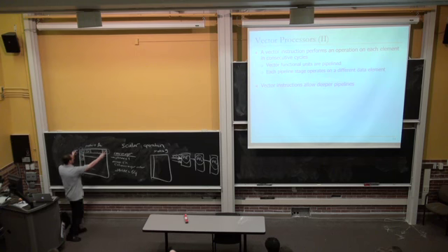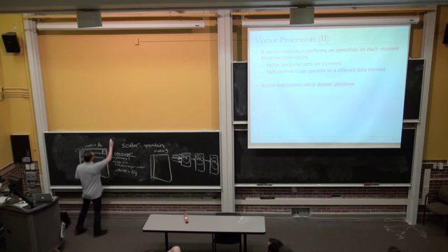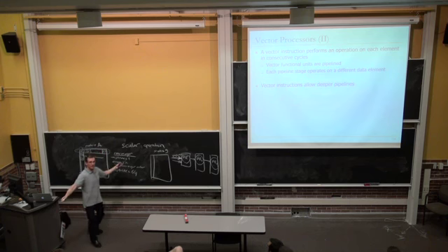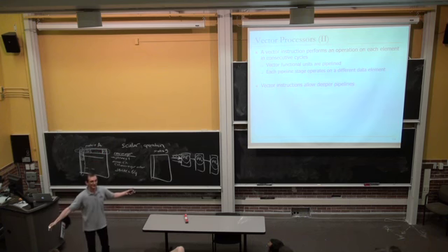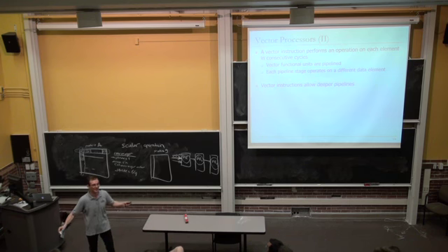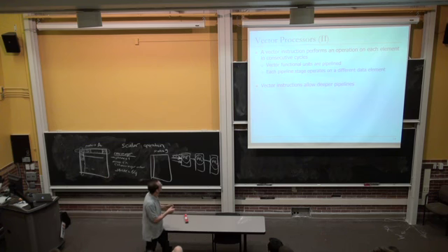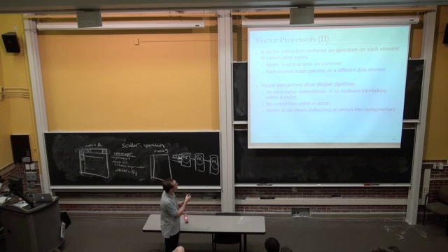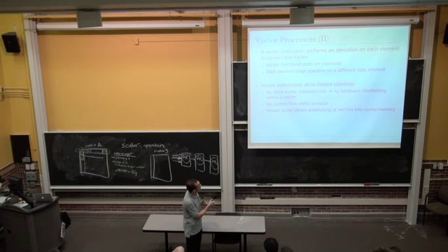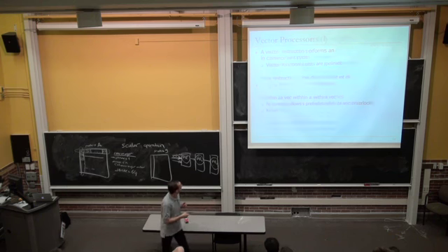In this case, let's say you can do all of the operations in the same matrix. Let's say your vector is 1,000 long. You can have a 1,000-deep pipeline, and there's no need for dependency checking because all the data elements are independent, right? You're doing add on all the data elements. Yes, there's no need to have hardware interlocking within a vector, no control flow within a vector, and known stride allows prefetching of vectors into cache and memory.